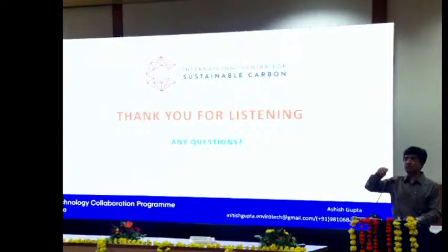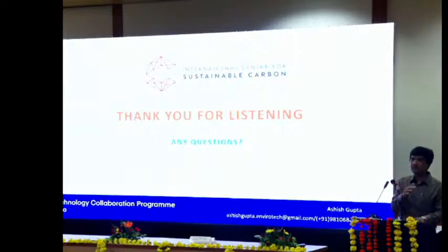But since you are the person in the field and you need to do the monitoring regularly for checking it also, you should know how it is being done. It's quite possible that many times the CEMS supplier will not share those values with you. But it does not matter. What is more important is you should be able to see that the values you are getting on the CEMS screen are the same as what you are getting with the manual system. If that is falling in the range, it means whatever factor has been fed into the system is more or less alright. But you should know it.